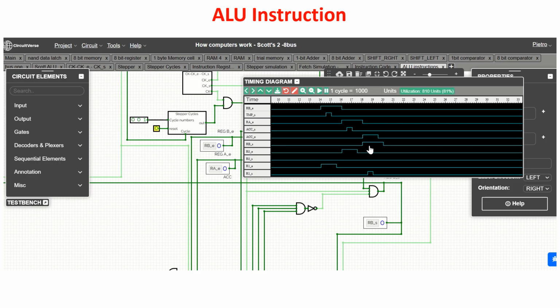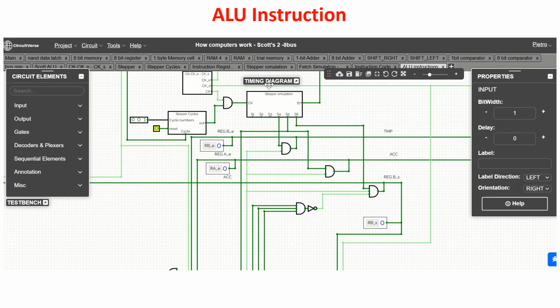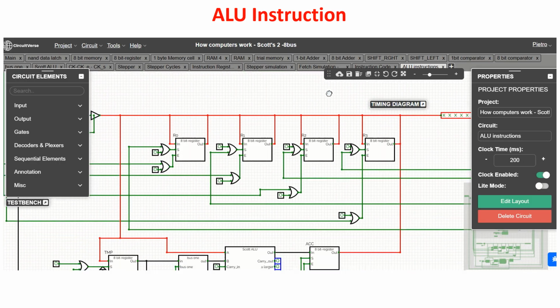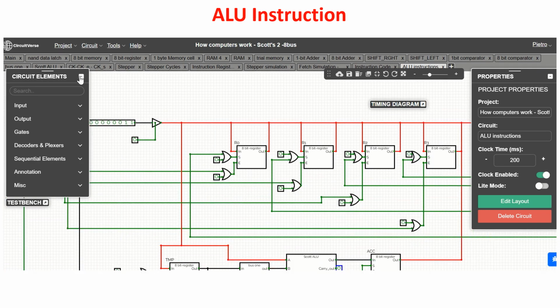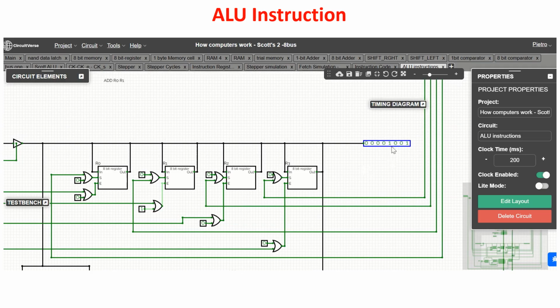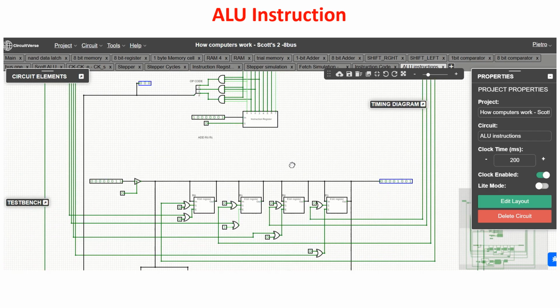In the sixth step, the last step, we give an enable pulse to the accumulator to put the result on the bus, and we give a set pulse to register 1 to acquire and store the result in register 1. Okay, so the timing diagram is okay, and we see if there is the number 9 inside register 1. If everything worked, it should be this way. So we put with an enable pulse the content of register 1 on the bus, and we see here there is the number 9, because this is 1 and this means 8. 8 plus 1 is 9, and so the simulation worked.